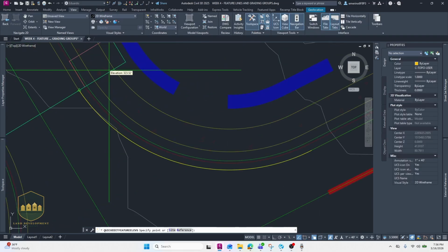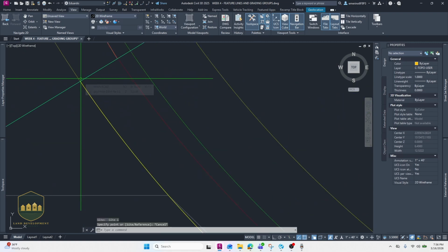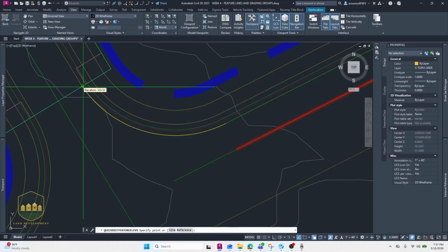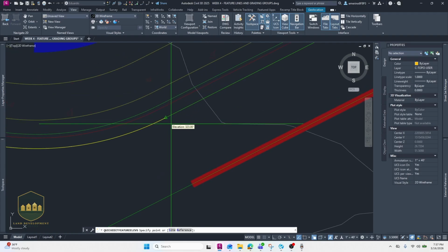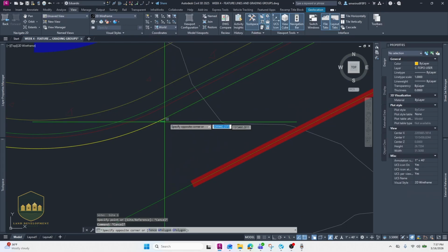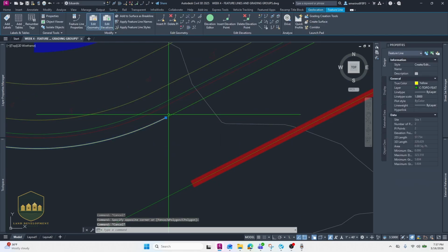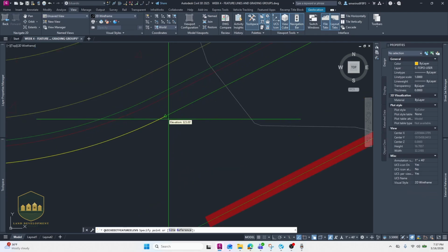What that does is this point right here matches this main road elevation, this Corridor A elevation, and then it's dropping down to 0. I need this point and this point to be the same. So I see right here, you can kind of see it popping up. It's 323, and then it goes down to 0. All I'm changing is 323.